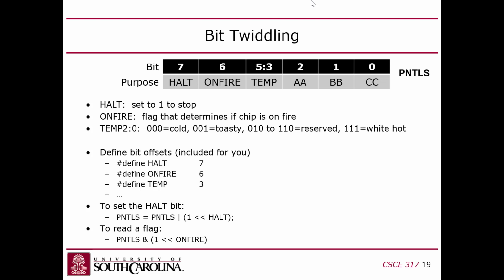Well, what you'd want to do, if I want to set it to 0, there's a couple of ways. I think if you do an AND, if you mask it, you'd want to make sure that there's a 0 in this bit position when you AND it. But you want to make sure that all the other bits are 1s. Why? Well, because you just want to flip that 1 bit to 0. You don't want to blow away the other bits.